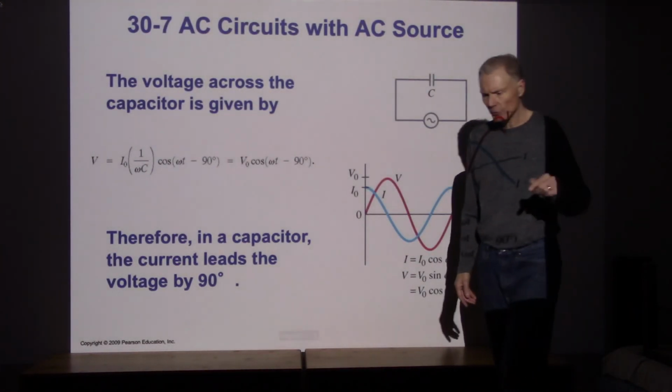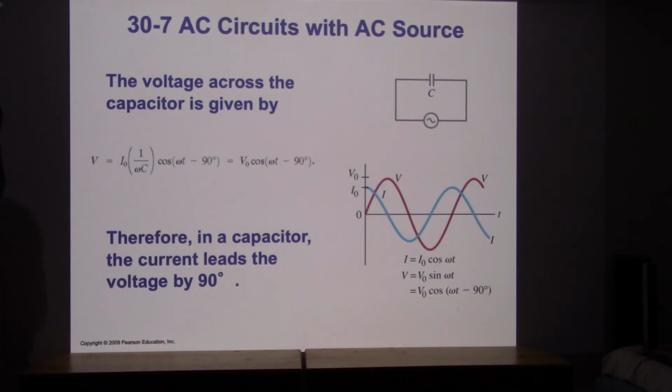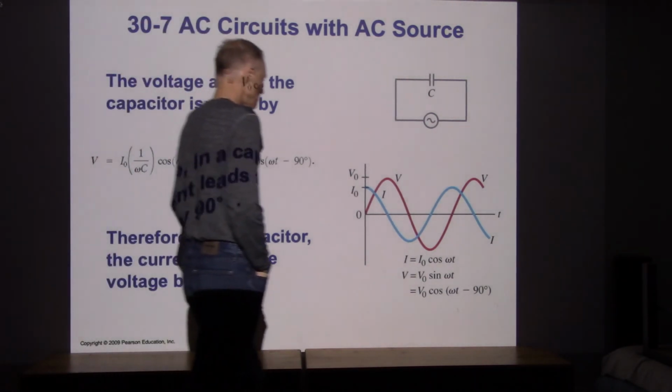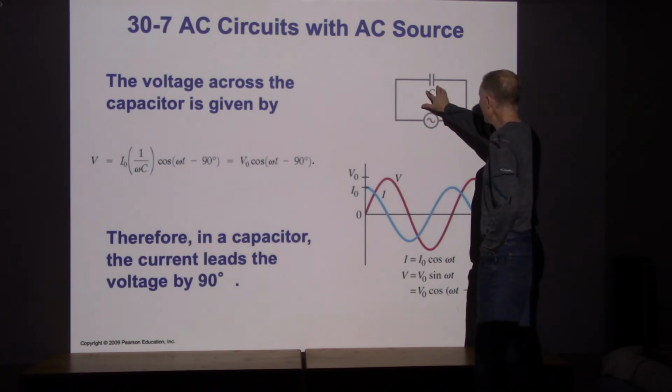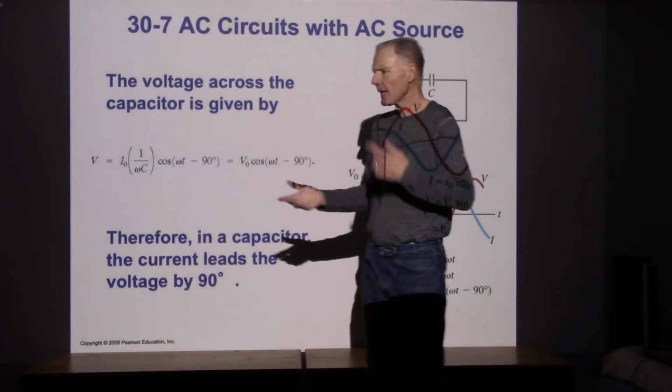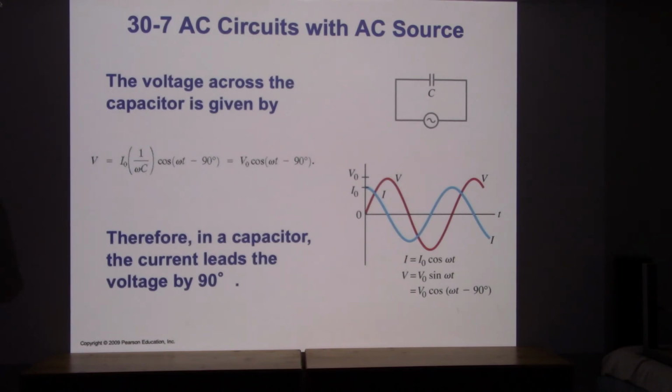All right, we looked at the resistor, we looked at the inductor, we did an example with resistors and inductors combined. Let's bring in the capacitor. Let's see what the properties of the capacitor are going to be. Now, if I have a power supply that's alternating current, and I got a capacitor, I can actually continually drive current because the capacitor will charge in one direction, but then it will charge the other way, and then it will discharge and charge the other way.